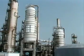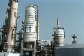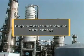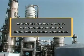Vacuum distillation is used for several reasons. First, one or more components in some liquid mixtures may decompose or be damaged at high temperatures. If such a mixture is distilled at high temperatures, an unwanted product may result. A second reason for using vacuum distillation is that running a tower at high temperatures requires more energy or fuel. Operating a tower at lower pressures allows the distillation process to be accomplished at lower temperatures, which requires less energy. A third reason is that a tower that's designed to operate under vacuum, and therefore at a lower temperature, can be constructed of materials that do not have to be specially made for high temperature operation.